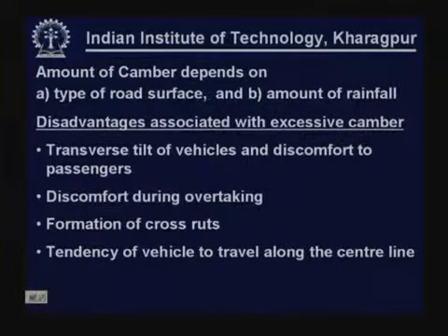Amount of camber depends on the type of road surface, pervious or impervious. More impervious surface, lesser camber is required, and also it depends on the amount of rainfall. Heavy rainfall, more camber or more cross slope will be required. Less rainfall, lesser camber or cross slope will be required. What are the disadvantages associated with excessive camber?